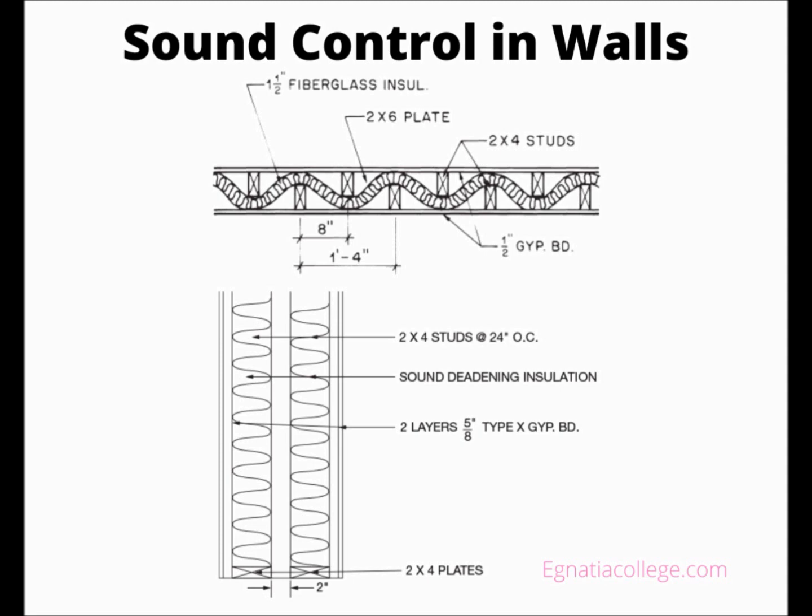Sound is transmitted by vibrations in any material, solid, liquid, or gas. To slow the passage of sound, a party wall must reduce the flow of vibrations. The materials used in the construction of most walls vibrate relatively well. Also, they transmit these vibrations to the air inside the wall. Sound can bend around corners and find its way through the smallest of openings. The air carries the sound to the other side of the wall, where it is transmitted to the air on the opposite side of the wall.